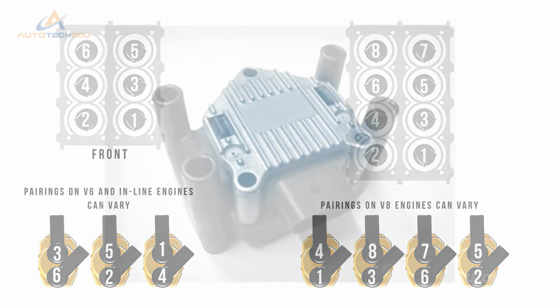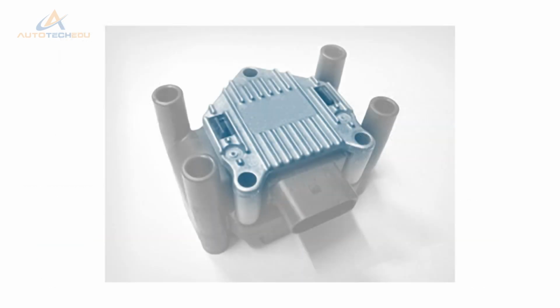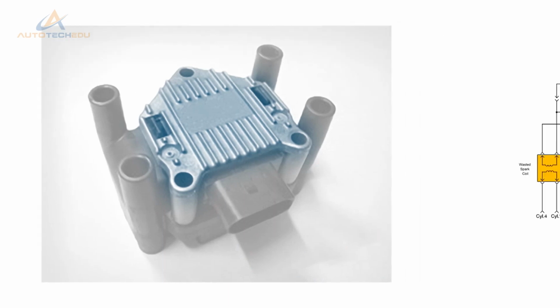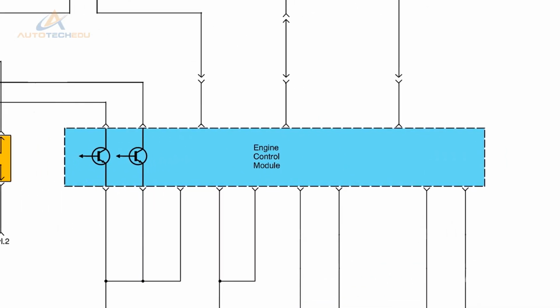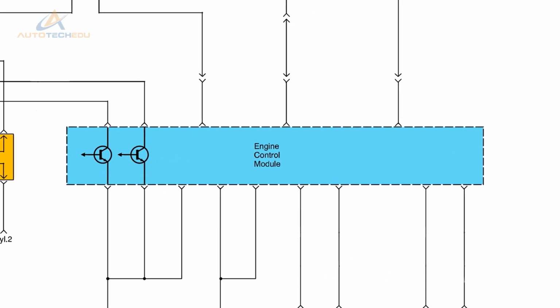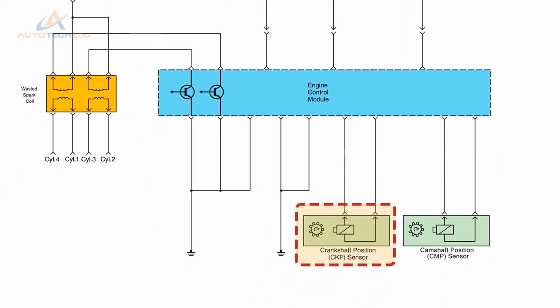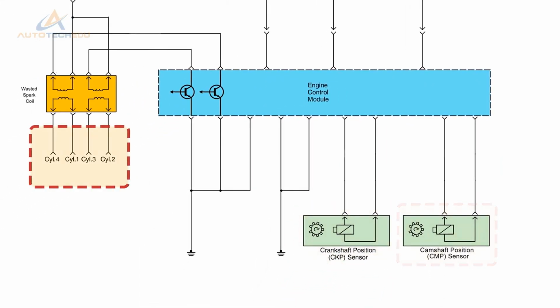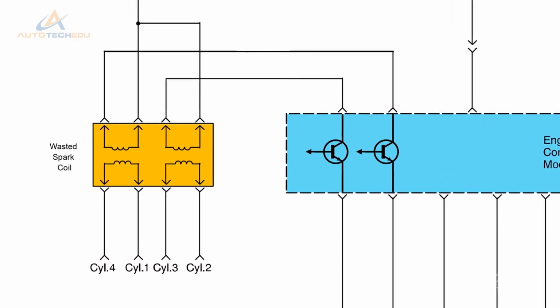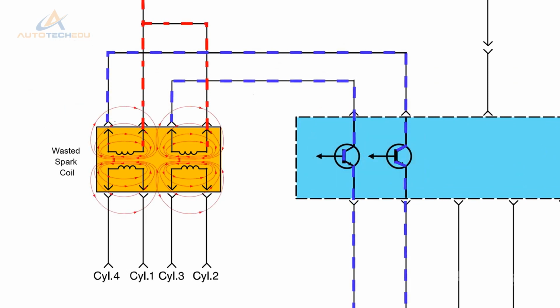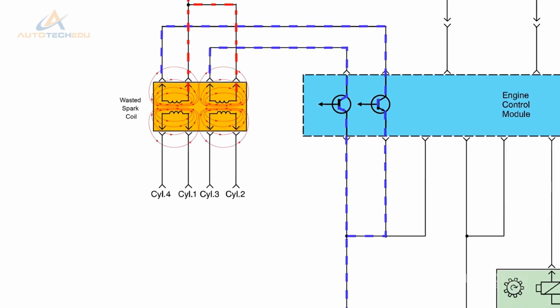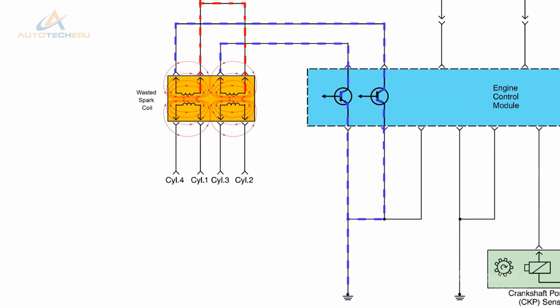An ignition module is still generally used for triggering the ignition coils, but later versions receive their control direct from the ECM. The control module synchronises the coil's firing sequences in relation to crankshaft position, camshaft position, and the engine's firing order. The ignition coil primary current is operated by switching transistors in the control module. These transistors or drivers complete the ground path for the circuit.